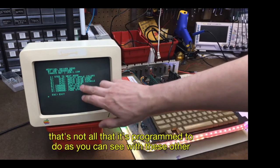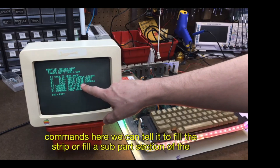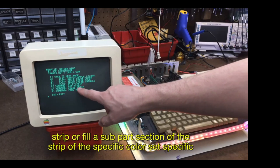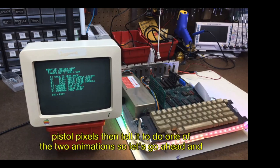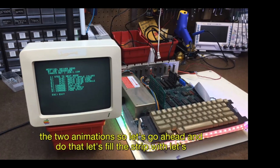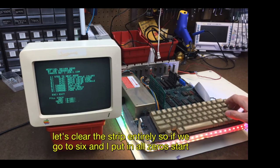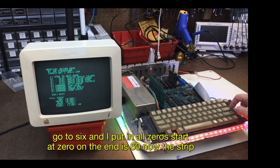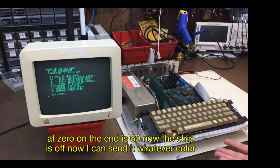As you can see with these other commands here, we can tell it to fill the strip, or fill a section of the strip with a specific color, set specific pixels, then tell it to do one of the 2 animations. So let's go ahead and do that. Let's clear the strip entirely. So if we go to 6, and I put in all zeros, start at 0 and the end is 60. Now the strip is off.